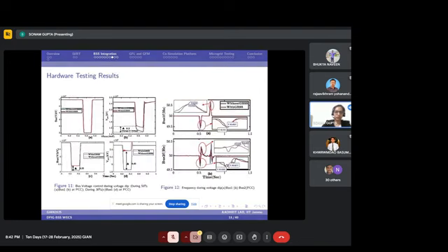So these are the results which we have for the 50% voltage dip and the 30% voltage dip. We have seen a significant change here with the battery storage system and without the battery storage. There is a change of 0.45% of the voltage when we have the coordinated control strategy. And when we look into the frequency, there is also a change in the frequency, but not that significant. So the main significant change is in the voltage.